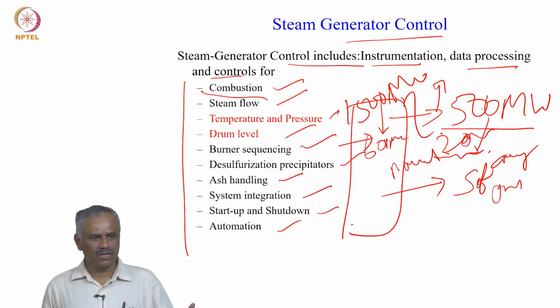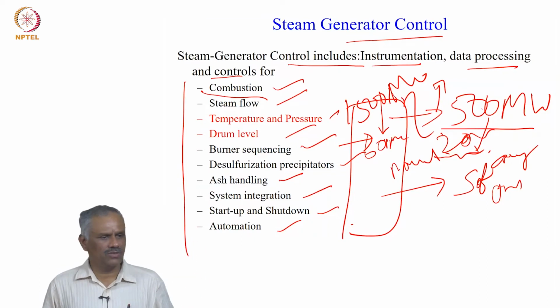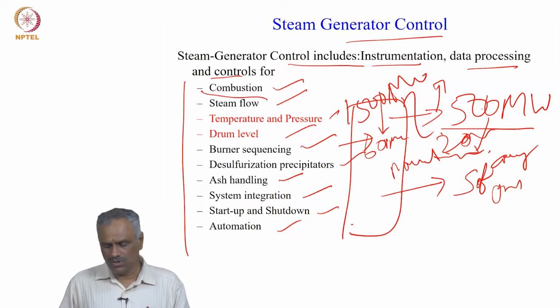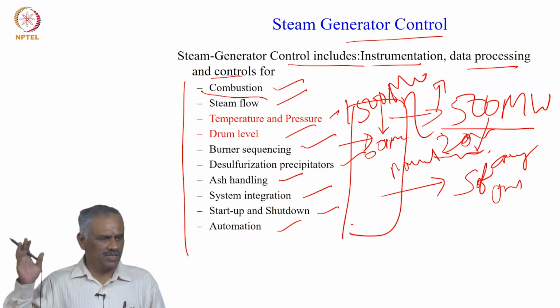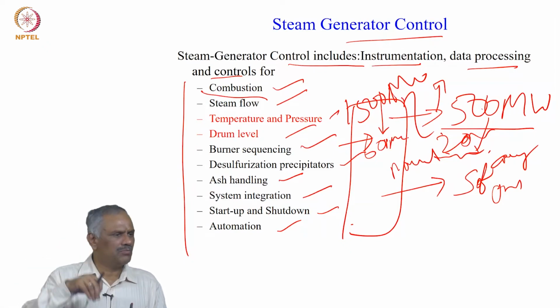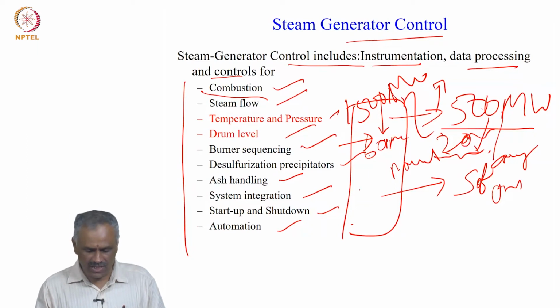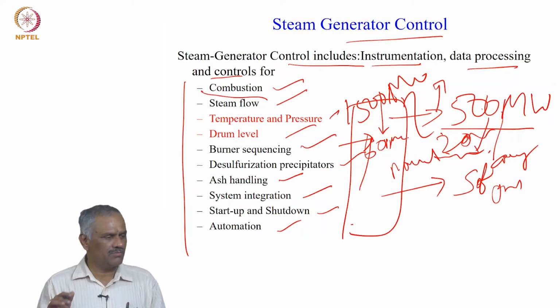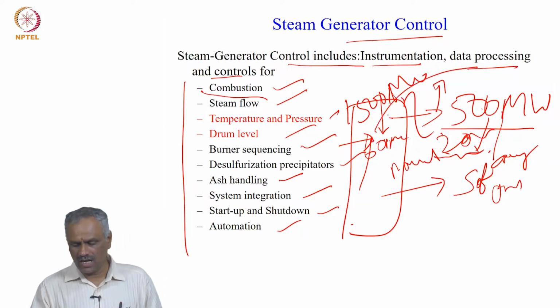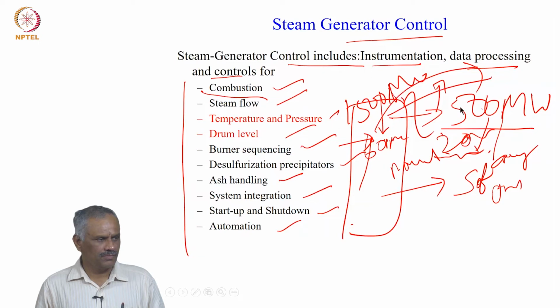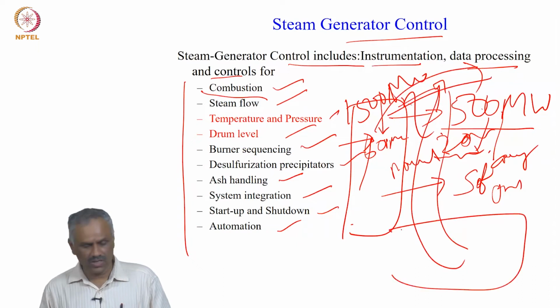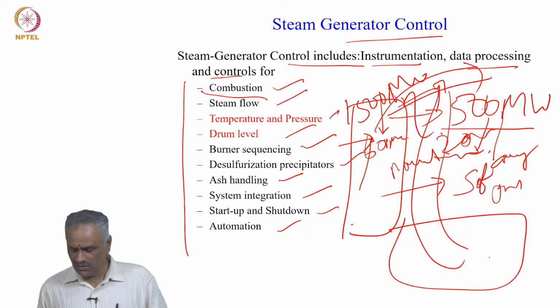The turbine you can run, but the boiler has its own inertia, you cannot keep up and do that. So some of these power plants, I have seen one, Hindujas and all these, they are operating at very part load condition, which becomes a very inefficient way of operation. So these people are coming up with, when this load comes down but we still keep the boiler at the same condition, what will you do with the extra heat which is produced? Then why don't we divert this extra heat into an energy storage, thermal energy storage, and whenever you need it, you take it back.